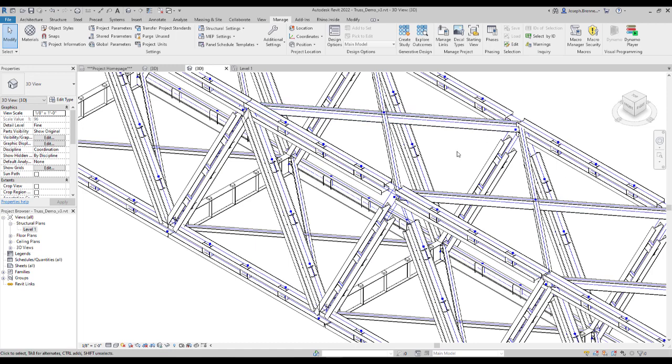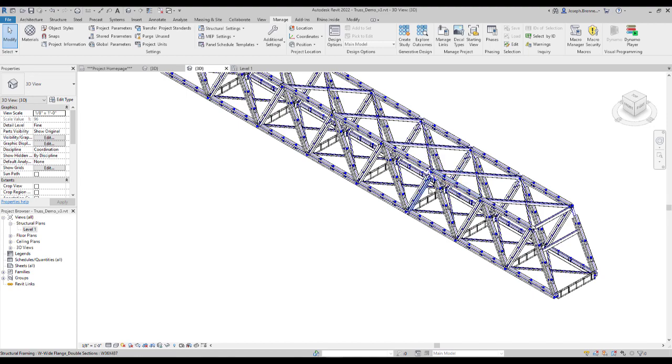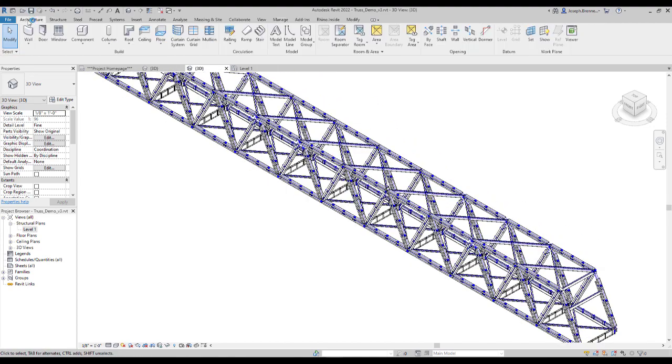Okay, so again, this is preliminary in terms of what we're developing here, and it can continue to be defined. One of the really nice things about this is now we can use all of our Revit tools to modify this. We can isolate certain members based on labels. We can modify that cutback distance for all the members in a certain group. So this is something that will need to be refined as you get into it, and as you make iterations on your own designs.